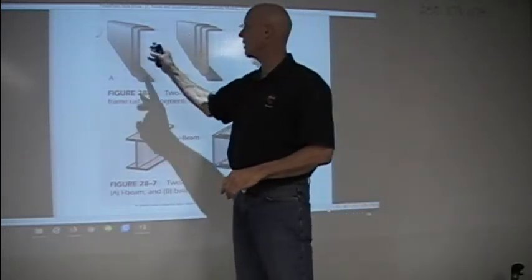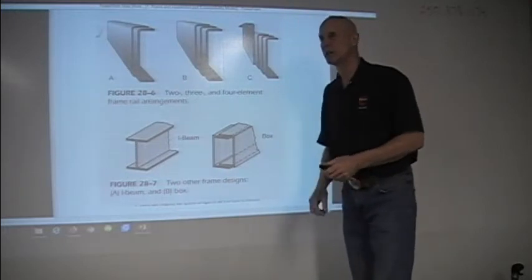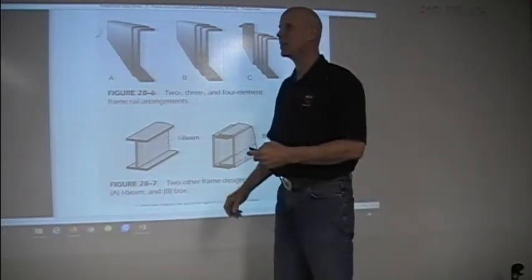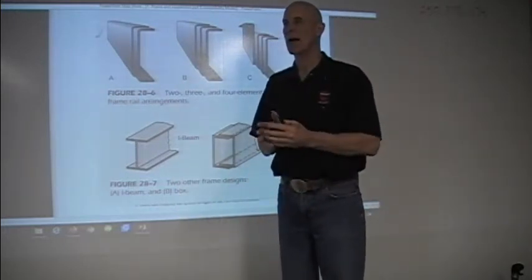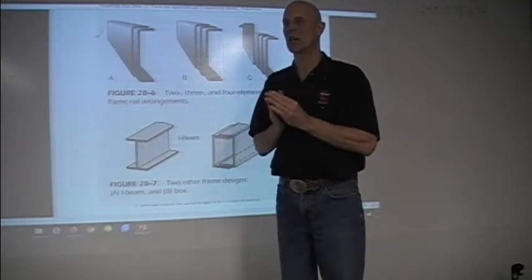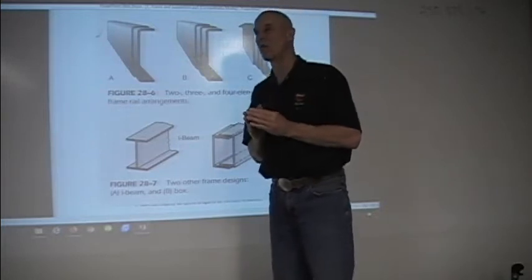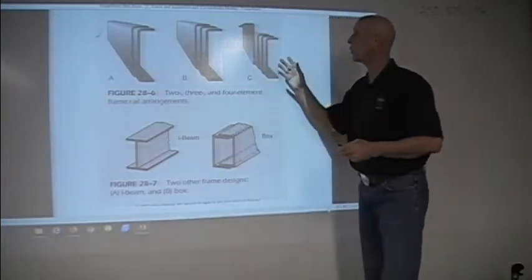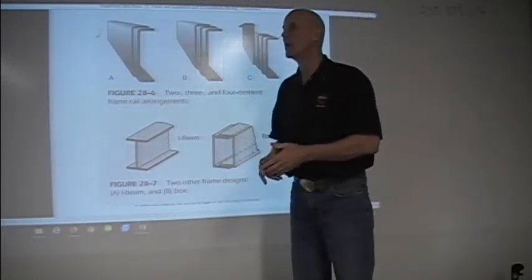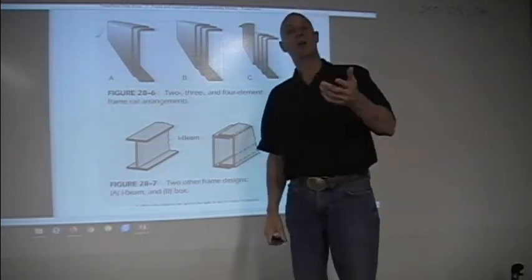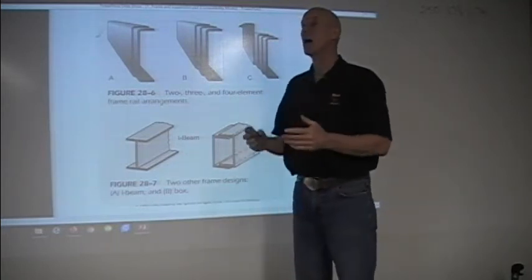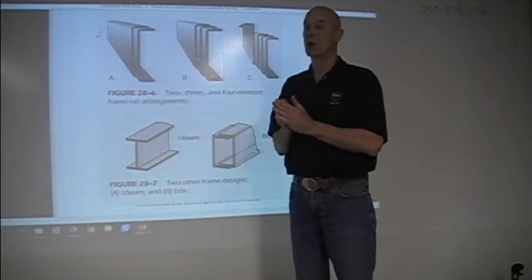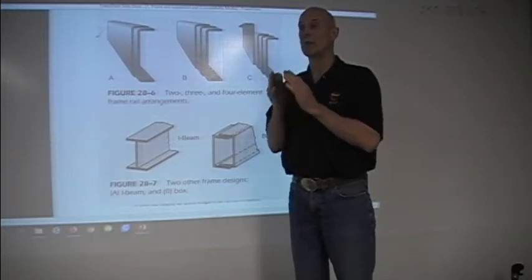So everything is usually steel. But if we have dissimilar metals, what can happen is we can have an electron exchange in there, and again, the weakest one is the aluminum, and it will dissolve faster. So anytime we're working with steel and aluminum, galvanic corrosion, that's what it's called. To prevent that, we either have to put tar on it, or we have to put something that will prevent the electrolysis from happening.